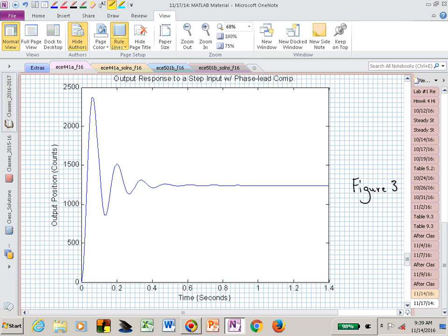So does that always mean that you need an integrator term when you're introducing a derivative term? And the generic answer is no. It depends on your specification. But in this particular case, if steady state accuracy is important to us, we may need the integrator piece. But in some systems, you may not be that worried about your steady state accuracy and more about your transient behavior.